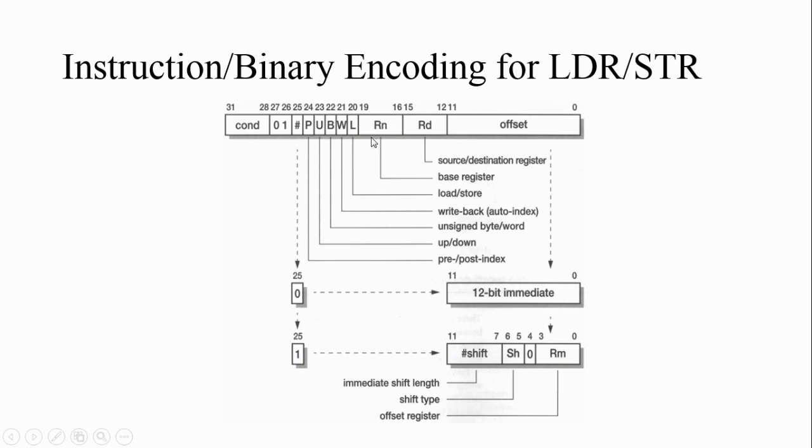You need to understand that you have a base address and an offset. When you add these two, you get the resultant address. From that resultant address in the data memory, you read the data, and that data should be stored into the destination register. The destination register is specified by a 4-bit value. Similarly, the base register is also configured by a 4-bit value.